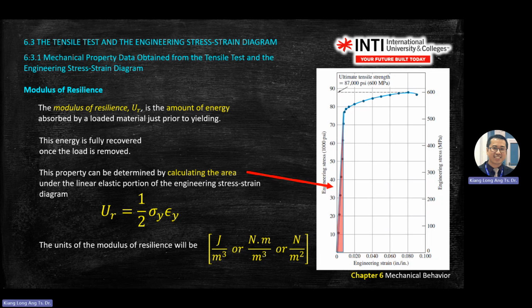Then here we learn about Hooke's law. Stress equals capital E times strain, where E is the modulus of elasticity, or Young's modulus. Strain, you have two: it can be longitudinal or lateral. The ratio of lateral and longitudinal strain gives you the Poisson ratio.